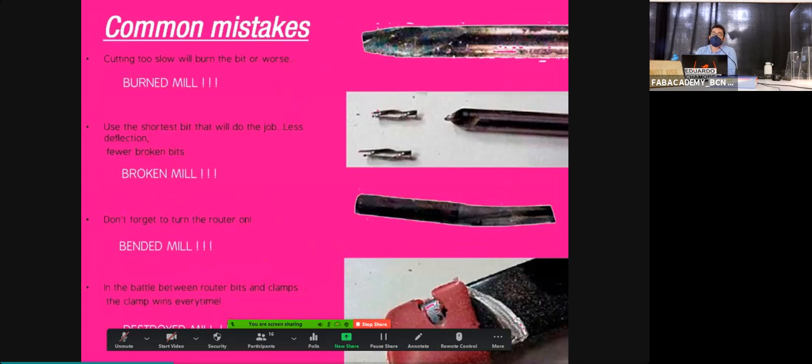What happens if you cut too fast? The machine cannot cut the material, so it breaks, or it can bend. For example, the machine can cut steel, yes, but you have set up the values for wood. What happens if you try to cut the screw that you are using to hold the material? The end mill cannot cut the screw at that speed, so it will break or bend. So you will damage the end mill also. Be really careful about undercutting or overcutting.